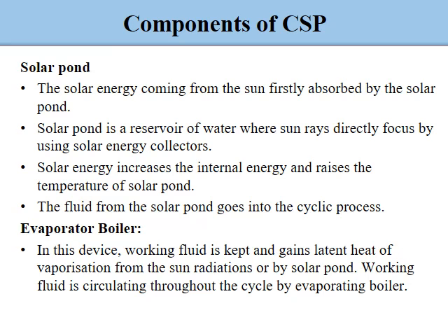The next one is the evaporator boiler. In this device, the working fluid is kept and gains latent heat of vaporization from the sun's radiation or from the solar pond. The working fluid is circulated through the cycle by the evaporator boiler.